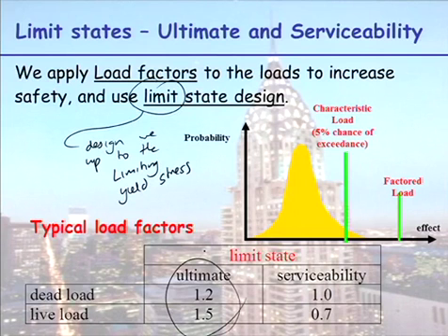So instead of saying, let's put the dead load on and design for strength, we put the dead load on plus 20% extra. Instead of saying, let's design for this live load, we go, no, let's put the live load on and an extra 50%. So we put bigger loads on, and then we design right up to the yield stress. So some people say, oh, my structure's being stressed up to 245. Oh, that's too close to 250. Let's put a bigger section in.